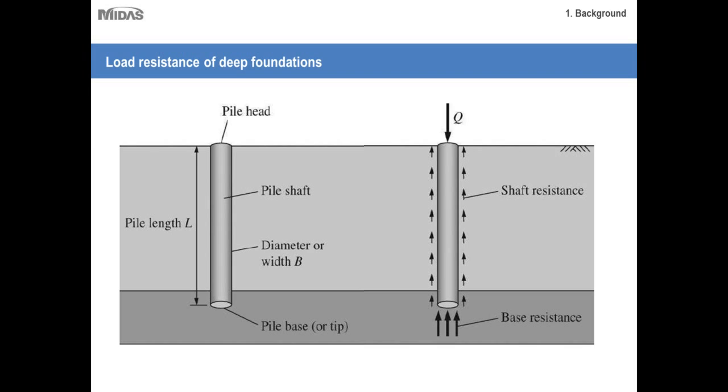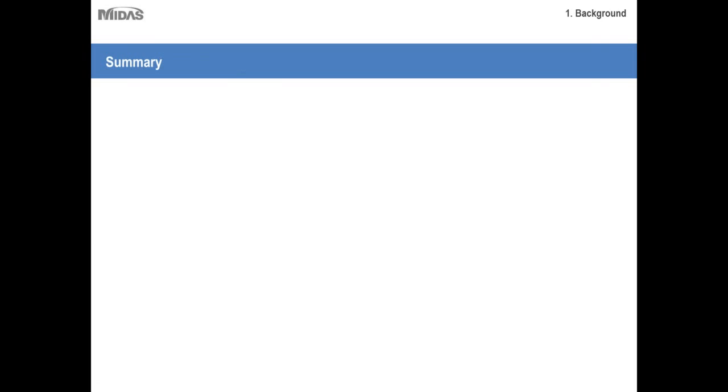So a pile can be designed as a skin friction pile or end bearing pile, or a combination of both, depending upon the layout of the pile, the dimensions, the material of the pile, the external load applied onto the pile, and the method adopted to install that pile.